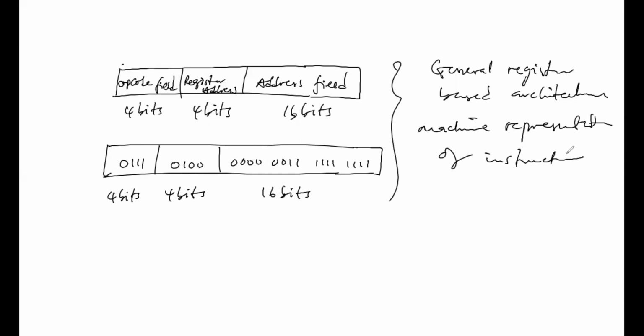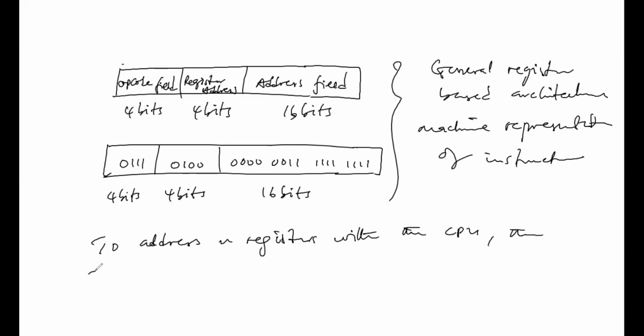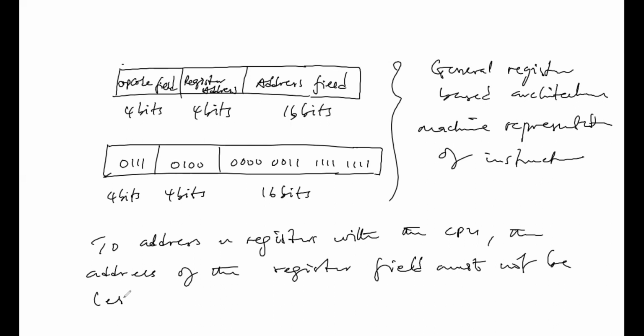And let's say for us to address n registers within the CPU, the address of the register field must not be less than log n base 2.